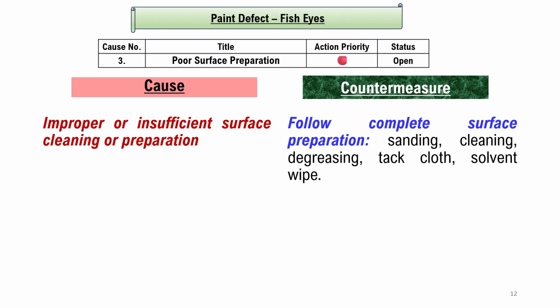The third possible cause, poor surface preparation, that is improper or insufficient surface cleaning or preparation in general. Follow complete surface preparation, that is sanding, cleaning, degreasing, tack cloth wiping, and solvent wipe.